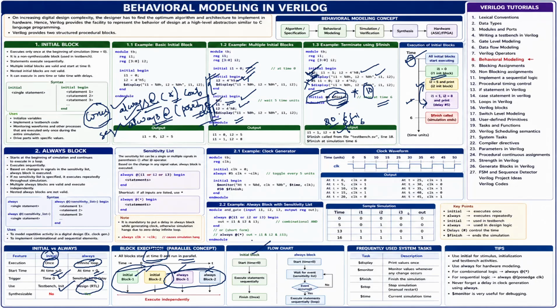Clear? So these are the system tasks. I will explain them later: $display, $monitor, $finish, $stop, all these things. Okay, $time. We will use them just for display purposes. We are using $display, and we have different regions. In which region is display executing, and then monitor? I will explain in the later slides.